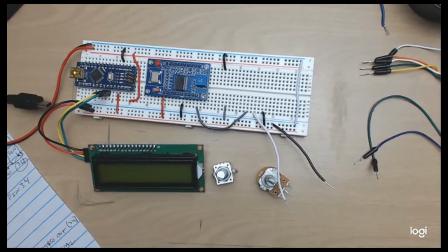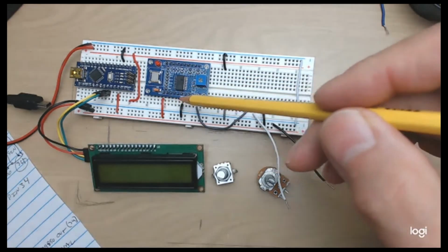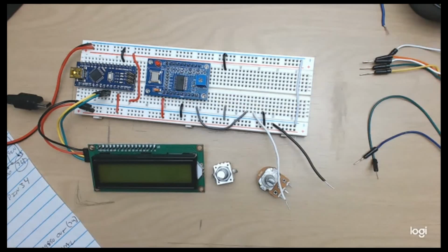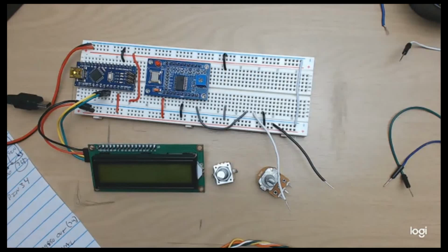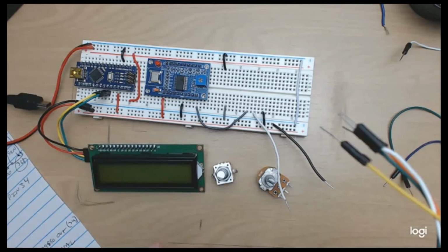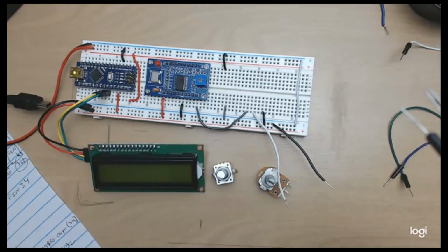So I turn the power off again, and now I got to make my connections. As I mentioned before, there's only 4 connections that we need to make. One is the clock, one is the frequency update, and those go right into this part of the board right here. The other is the data pin, and the last is the reset pin. I made up a little twisted wire cable here to make it a little easier for me to deal with. And I even wrote down where I wanted the color codes to go to make this quick.